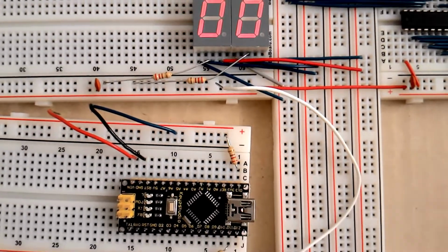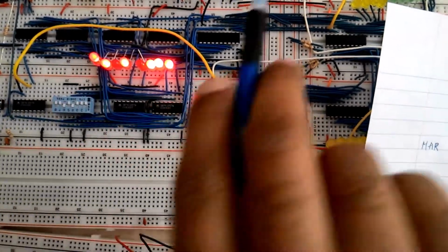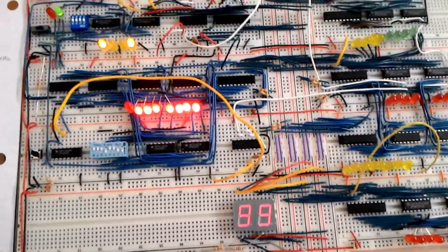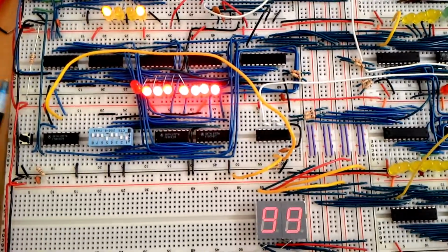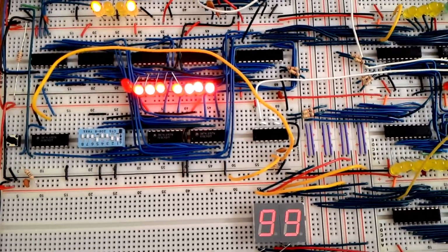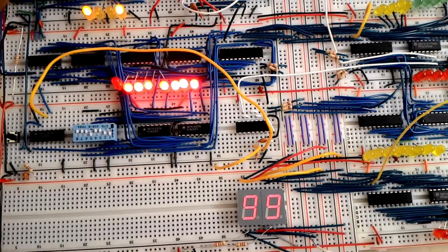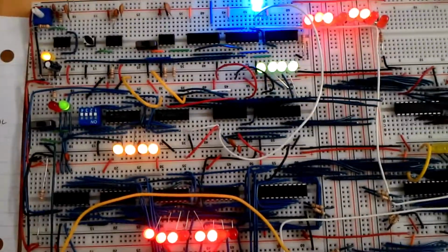instead of a hexadecimal value. I will pause this video for now and I will record these 7-segment hexadecimal data values to our RAM, and then I'll show you again how this data comes to our display unit. I have programmed the values in our RAM here, and I'm going to show you the values that appear in our 7-segment display. I'm going to start the clock, and we can see that when the binary counter starts